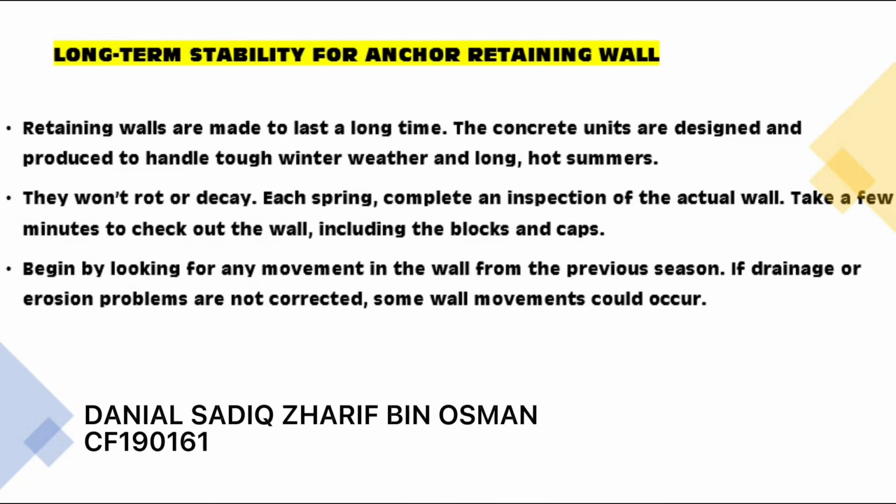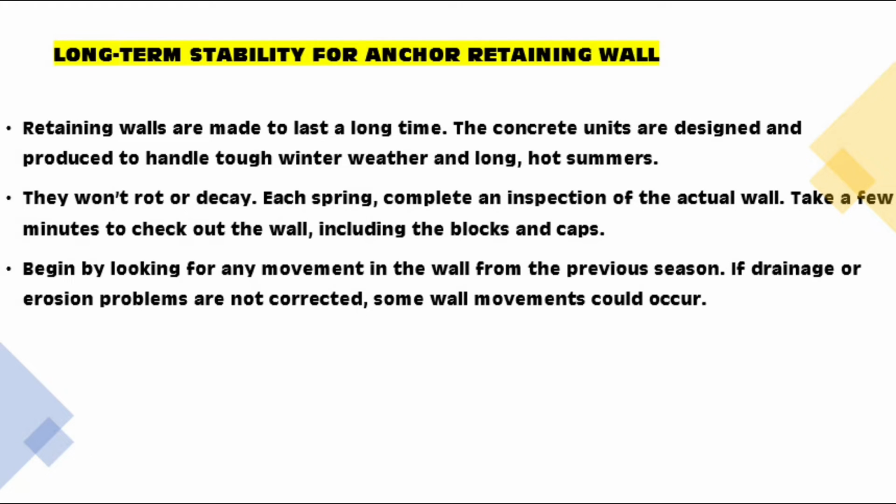I will present about the long-term stability for anchor retaining walls. Retaining walls are made to last a long time. The concrete units are designed and produced to handle tough winter weather and long hot summers. They won't rot or decay. Each spring, complete an inspection of the actual wall. Take a few minutes to check out the wall, including the blocks and caps. Begin by looking for any movement in the wall from the previous season. If drainage or erosion problems are not corrected, some wall movements could occur.